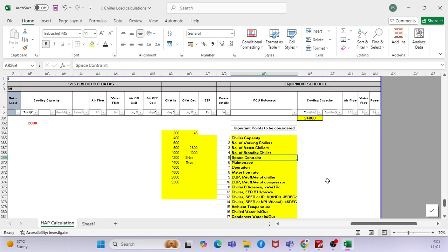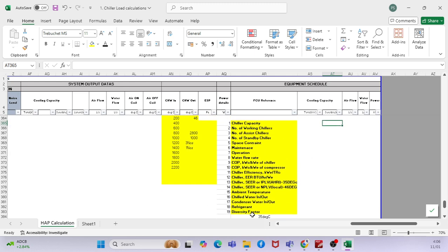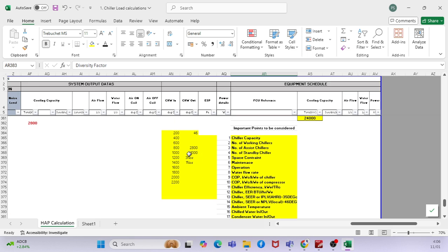Also, you can plan one more way of selecting the number of chillers. You can also choose in a different scenario. When you select the number of chillers or the capacity, say for example, assume that I have one building and it will not be operating at 100 percent all the time. Like I have 70 percent, 80 percent operations. At that time you will apply a diversity factor. That is called diversity. So even then it will come down in steps.